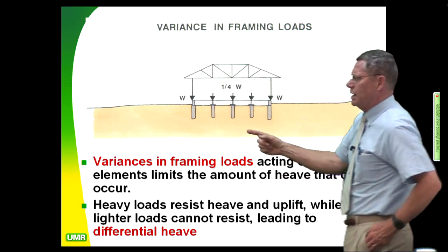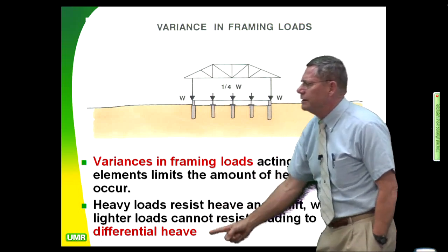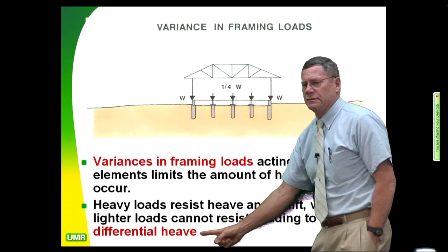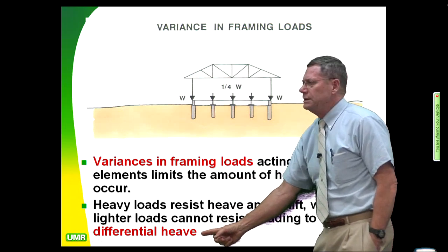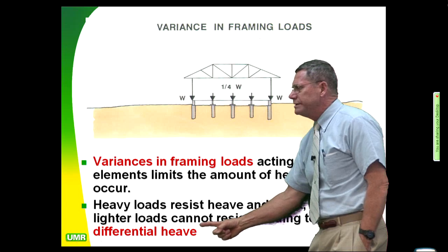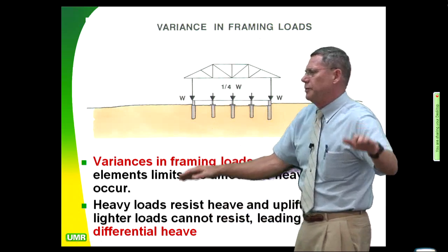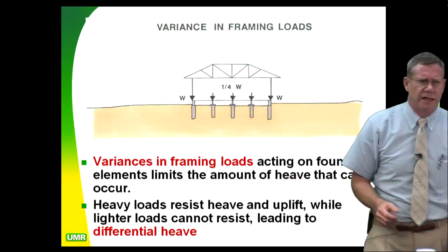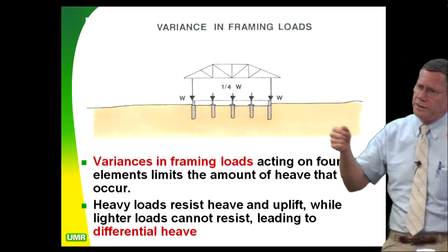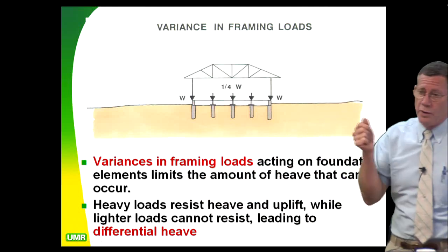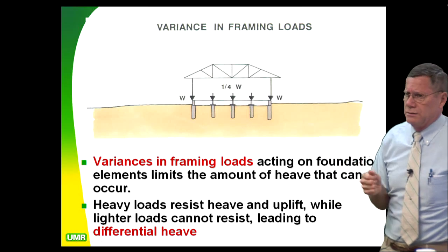So our enemy in geotechnical engineering is differential heave. We're not going to get rid of the swell, but what's going to do structural damage is when one part is lifting more than the other part. We're going to lose our functionality. We're not going to be able to open the doors, open the windows, stuff like that, and we're going to have unhappy clients.